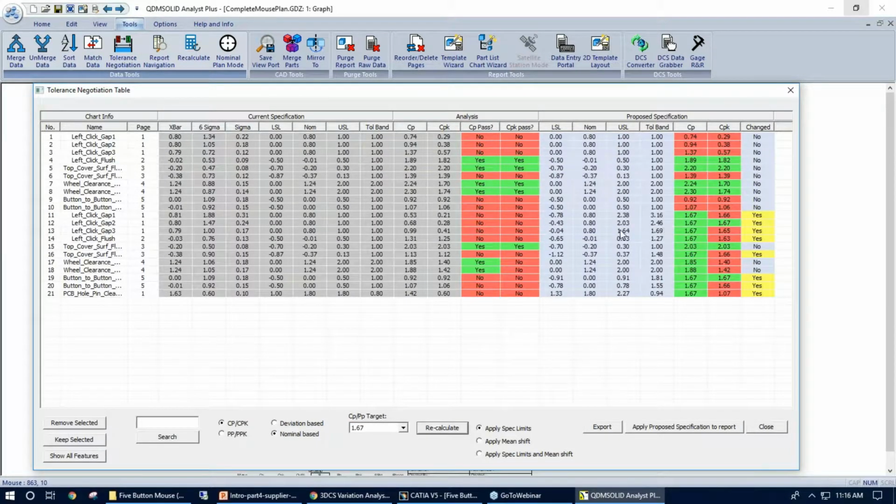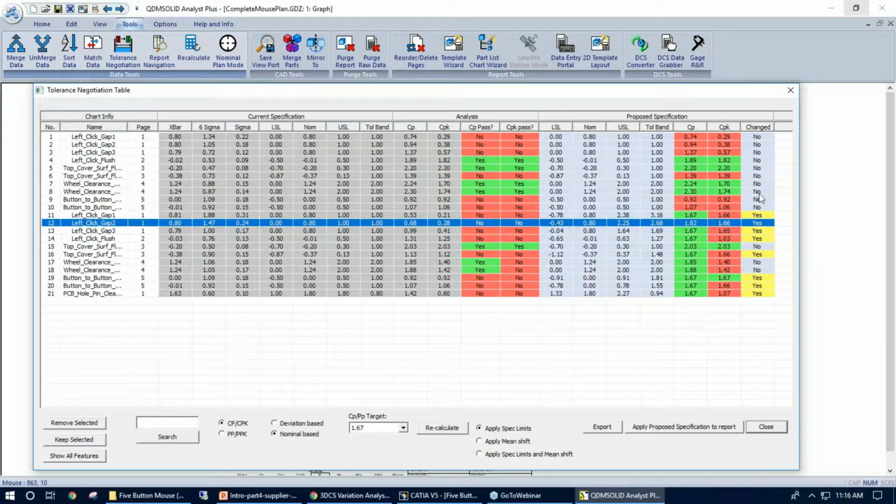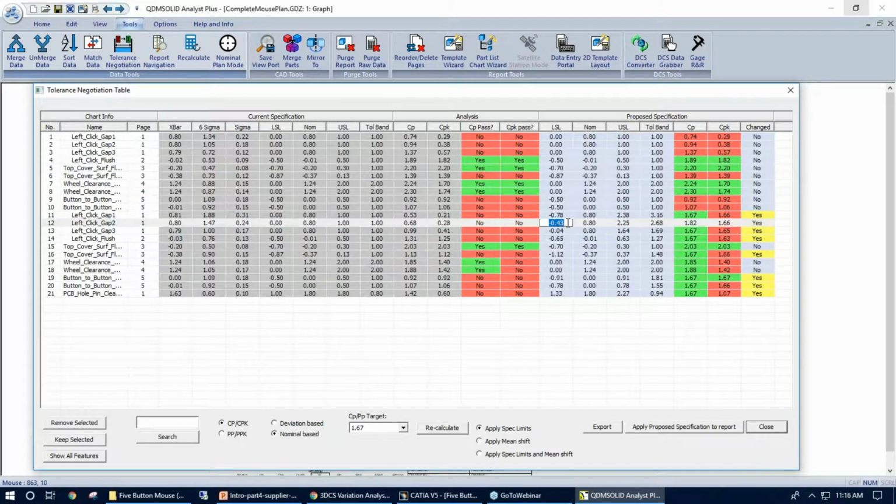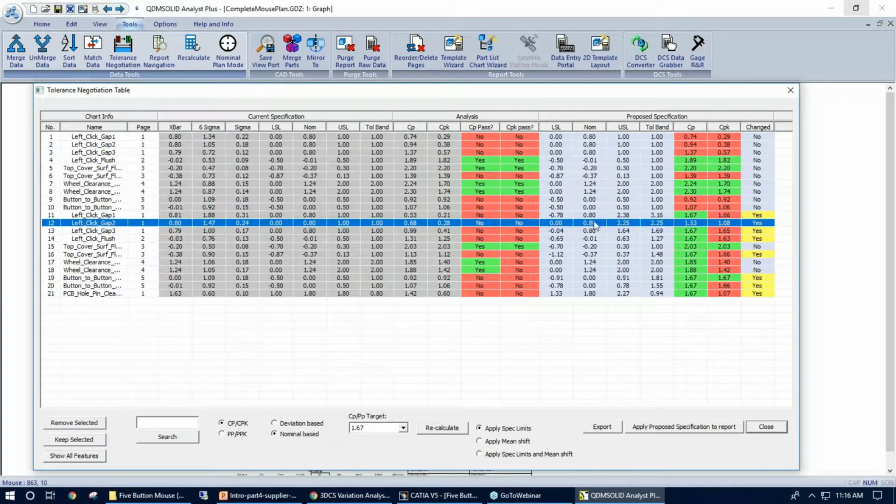recalculate. We can also type in different spec limits. So if a supplier in this case called and said, or is working with the OEM, you can type in a limit here. If I just wanted to go 2.25, now we can see we've created a 1.82 CP, or you can even reduce the lower tolerance to be 0. What is that going to produce? So it's a little bit of plug and chug involved if you'd like to kind of look for certain numbers.